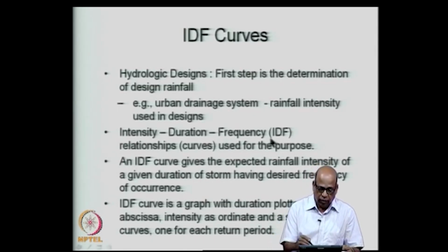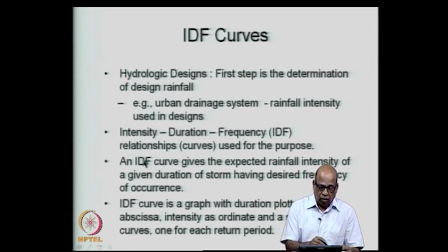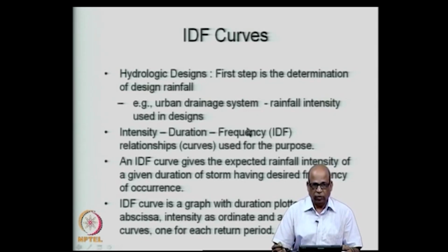So, the frequency or the return period is a matter of judgment of the designer based on the importance for which the hydrologic designs are meant. You may have a very critical installation like a nuclear reactor or some such thing, for which you need to provide flood drainage, in which case you may want to use a 1000-year return period flood and so on. So, once you fix the duration, we must have a relationship between intensity and frequency, and that is what we will do in the IDF relationships.